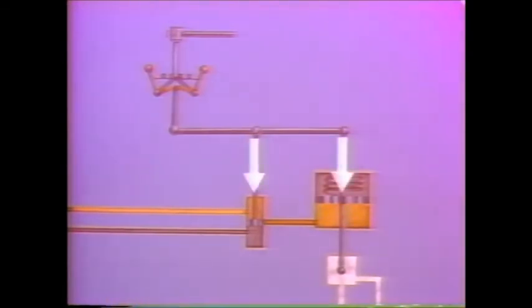The combined downward movement of the crossbeam and the piston closes the servo valve, so that oil can no longer escape. The control valve is now held in a new position and the turbine continues operation. Intercept valves use a similar system but have an above normal speed set point. Thus, at normal speed, they're wide open.